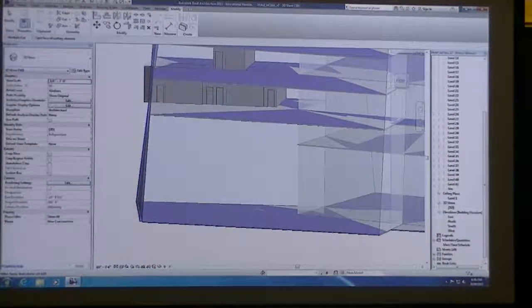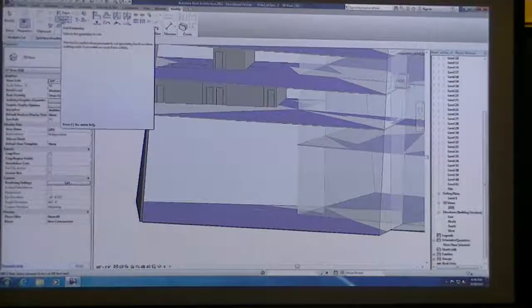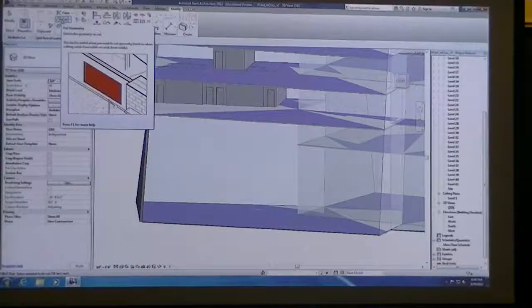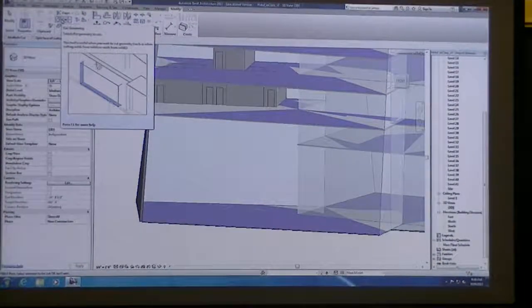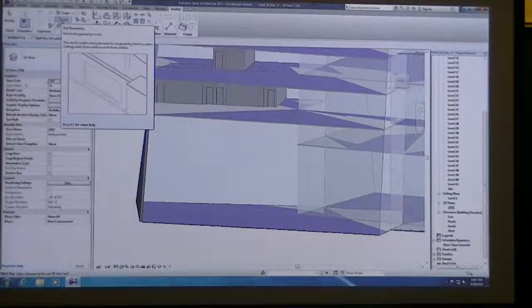I'm not sure. And actually, what the video is showing you is that if you had a void that you cut out of a mask, and for some reason that void, you know how when we worked with voids before, sometimes that void worked and sometimes it didn't? That's basically what this cut command does: it allows you to rehost that void and cut out a void element from a mask.